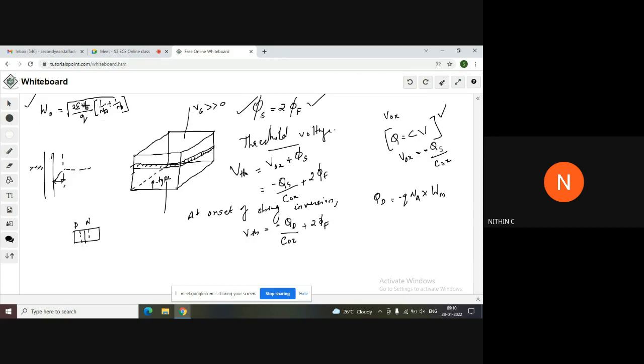So here in this case, this is actually V0. Now let's look at what to replace. When we come to our MOSFET case, how it will change, that is what we are going to see. This V0 will be changed to phi S. Phi S will be V0. And this ND term will go because we are not having an N region. We are just having the P region. That's why we can ignore this ND term.